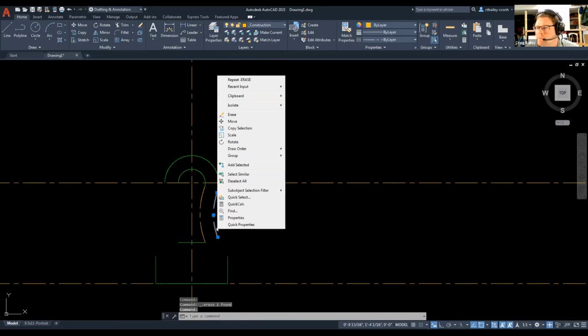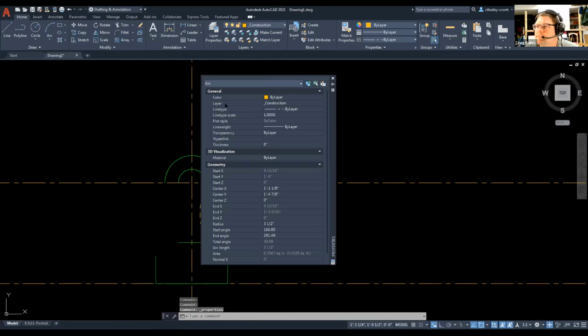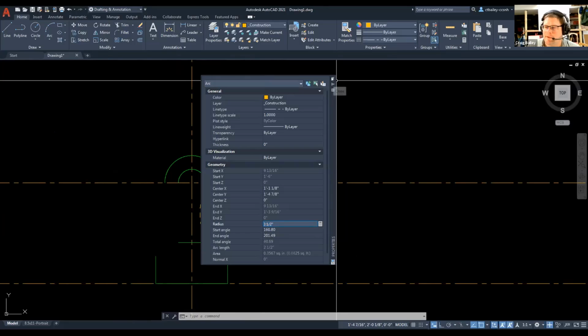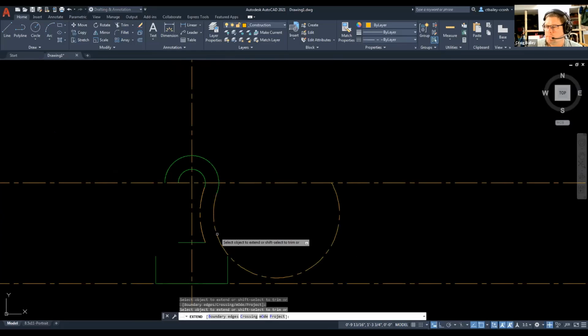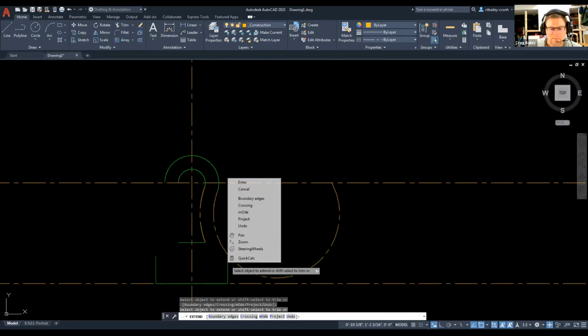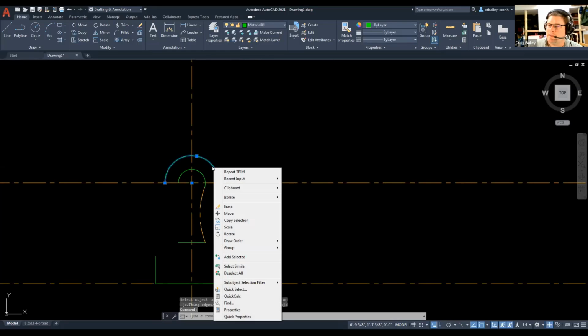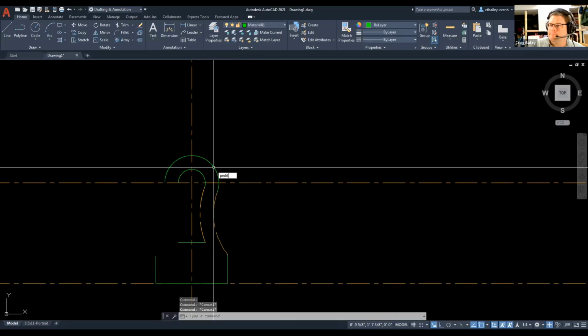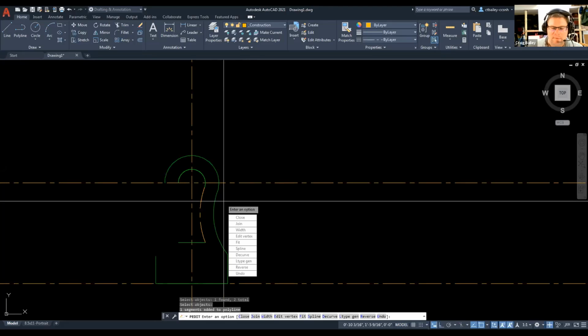Check the radius properties. We'll pick that arc. We'll go to properties. Pull the properties over here. Radius is 3.5. Perfect. Okay, it just doesn't get any better than that, all right? And we're going to extend it. Like that. Extend that one. Trim the excess tail. I'm going to polyline edit this. So I'm going to start with the P edit. This one, yes I do. I'm going to join it here to here. Enter. I'm going to trim